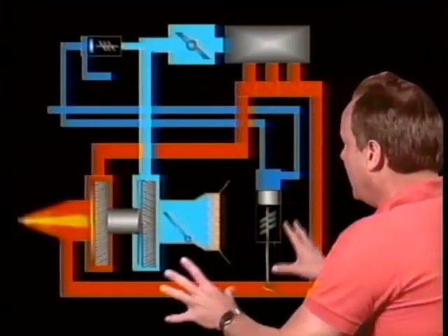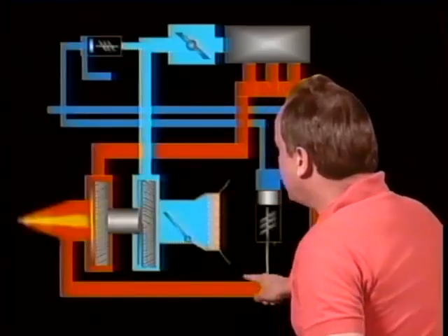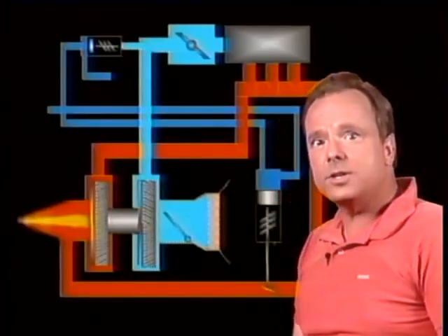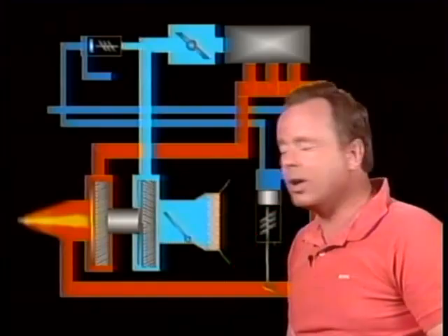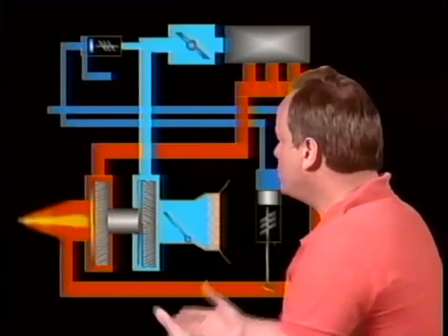All right, now let's take a look at a couple types of systems they have. One is a sea level boosted system, and we need to explain how the wastegate is controlled. We're going to talk about a sea level boosted system, and we're also going to talk about a turbo normalized system. The difference between those two systems is how the wastegate is controlled. By the way, the definition of a sea level boosted system is one in which you have boost on takeoff, in other words, more than 30 inches of manifold pressure on takeoff. It's called a sea level boosted system.